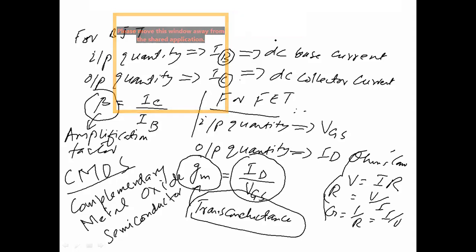So that is why we don't need to determine the current gain for FET amplifiers. Clear? So the important circuit features are voltage gain, input impedance, and output impedance. And the current gain is an undefined phenomenon. That is why we don't need to determine the current gain.